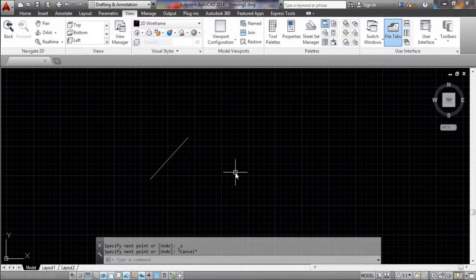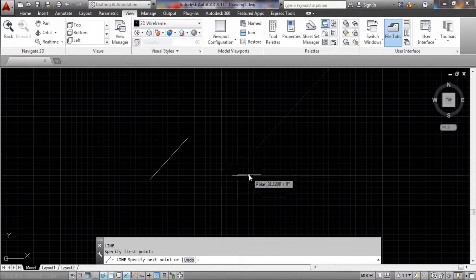And when we close the dynamic input option and enter the line command, now I can't see the length of my line. I am writing 120, but I want to specify also my angle. So how can I do it? Before writing 120, I'm deleting it. Write the at symbol and then write your length 120, comma. Our angle is, for example, 68.